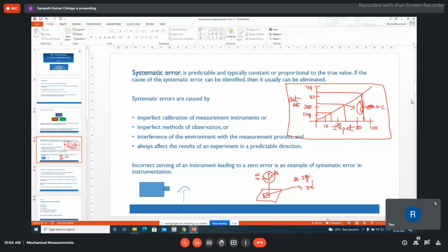So the Seebeck effect will tell you that when two dissimilar materials are joined together at two different junctions and their temperatures are different, EMF is produced. So this side you are having a very high temperature, that side you are not having a high temperature. Because of this delta T, a voltage will form, and with the data acquisition system, you are actually referring this voltage to a temperature. So whatever change in the temperature, you are measuring, and the data acquisition system will give you the temperature sensed by the thermocouple. So that is your output.